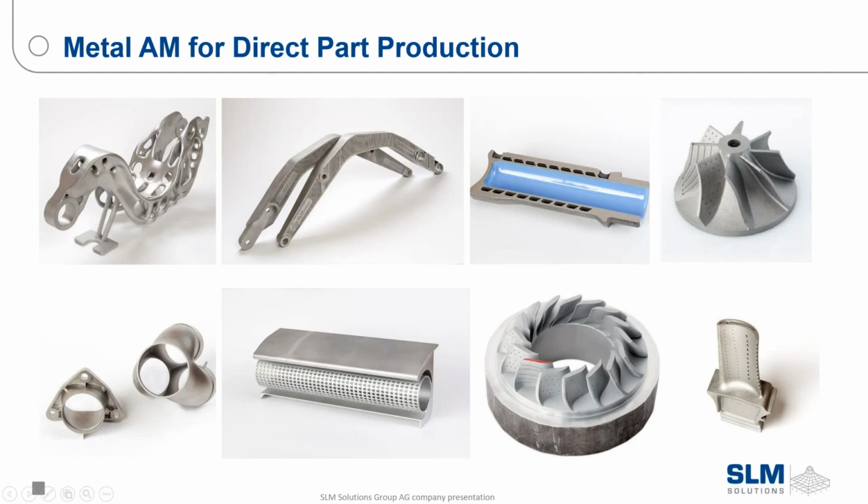What is the recoater time for the SLM 500? The recoater time for the SLM 500 is about 8 seconds. And that's also, with each layer, it's only one recoat versus other machines where the recoater has to travel twice. Okay.